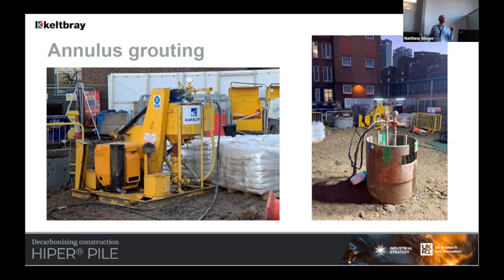It's a correct statement that concrete is more of an insulator. That's why we build basements out of it, because it keeps the cold out and keeps the warm in. The advantage of the Hyperpile as a precast or under cast in situ is the barrier is now only 200 millimeters thick. So we can actually get the heat to and from the ground much quicker, which is why it's 60% more thermally conductive. The normal pipes that go in solid piles sit in a great big solid mass of concrete, a very, very poor conductor of heat. Here we've got a water or a thermal grout, which is very highly conductive and good at storing energy. We only have 200 millimeters of structural concrete to get through to get the heat to and from the earth.